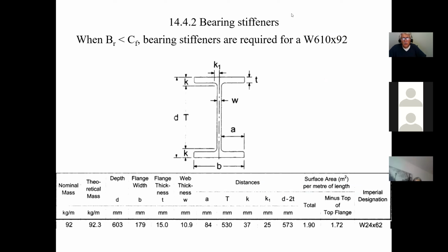And of course, what's going to happen is when you put in your stiffener, you're not going to go right up to the edge because you have this little fillet here. You're going to put your stiffener like this, and your stiffener is going to go here like this. And of course, that's how your stiffener is going to be. And after that, you're going to be welding these all the way around on both sides, and you're going to connect the two of them together.